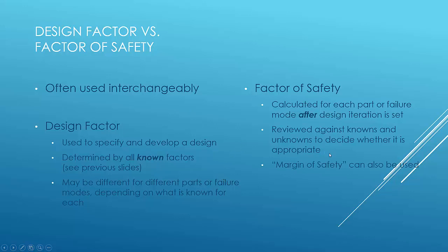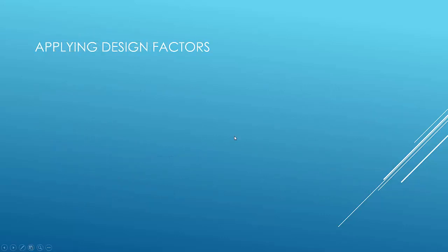There's another thing called the margin of safety. That's a slightly different calculation, but it's also an appropriate way of considering these design factors and factors of safety. And it's always best to refer to those standards from the different societies to determine the appropriate factor of safety. It's hard to go wrong with that. Okay, how to apply the design factors. Well, first off, if you're using codes or whatever, you should review your tables.